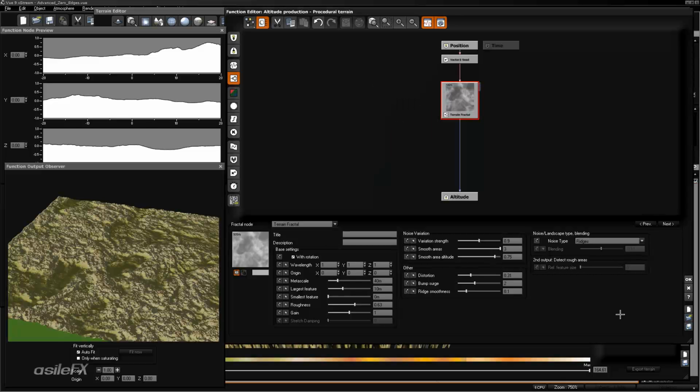Now, in case you are not quite sure why that multiply by constant is added for the object parametric modes within Vue 9 and was never needed in Vue 8, that's because of the scale change for terrains. Terrains basically output a correct scale now, except a procedural terrain on the z-axis only outputs a view unit. The actual amount in the real unit is not correct. In that case, you would have to use a view unit to match things up in graphs.